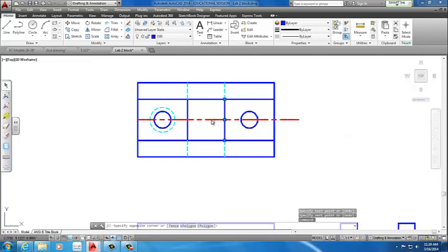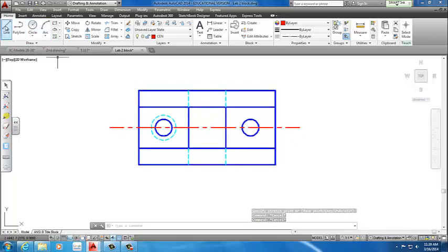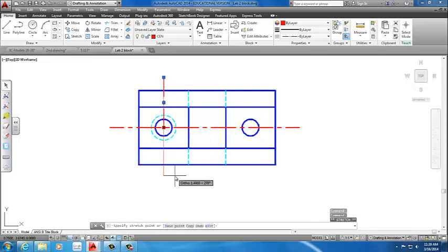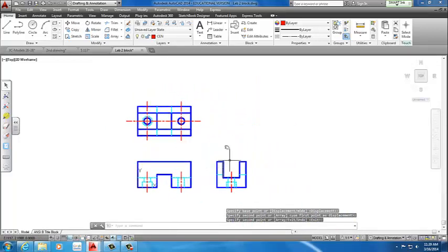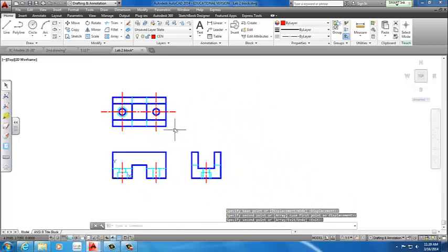Again, you have to stretch it to overextend the object, otherwise people will get confused about what that line is. We do the same thing with the circles, so we overextend and select the blue point and stretch it out. We make a copy from the midpoint of the circle to the center of the circle, creating our complete object.